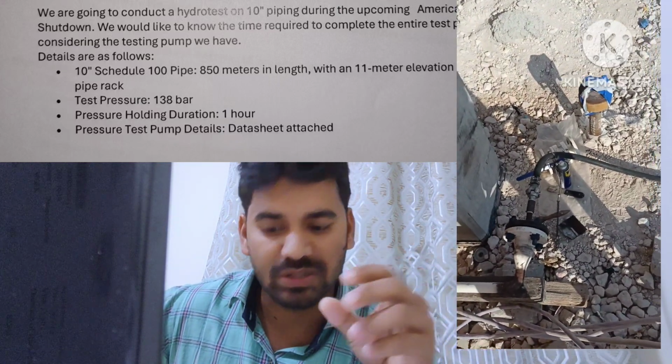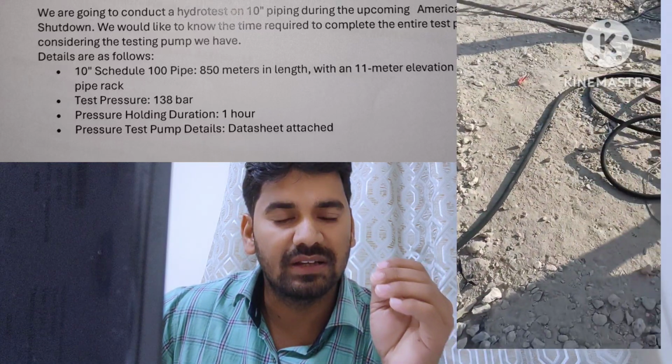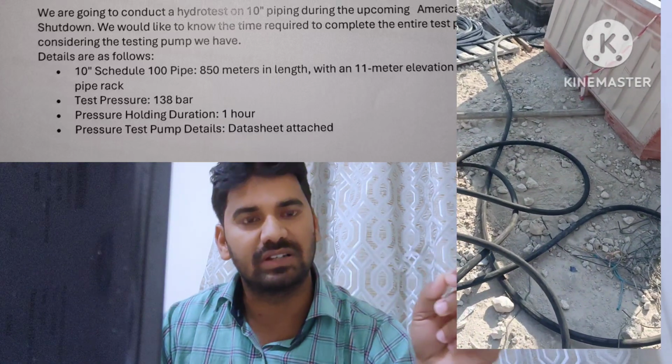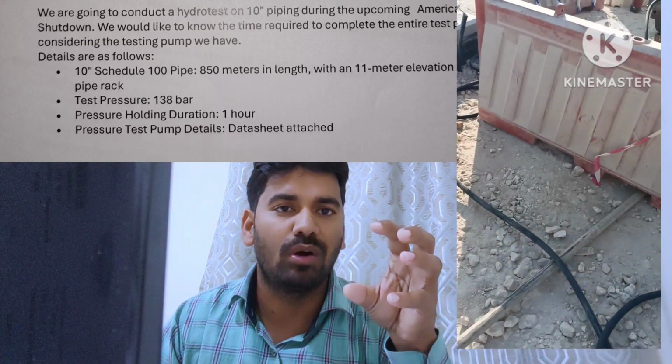He is giving me the information related to the test pressure. The testing pressure is 150 bar. Bar multiplied by 14.5 gives psi, and bar is also equal to kg per centimeter square. The pressure holding time is 1 hour. He wants to know exactly how much time it will take for the hydro test, because he has limited time. So he wants to know exactly how much time is required for this testing.